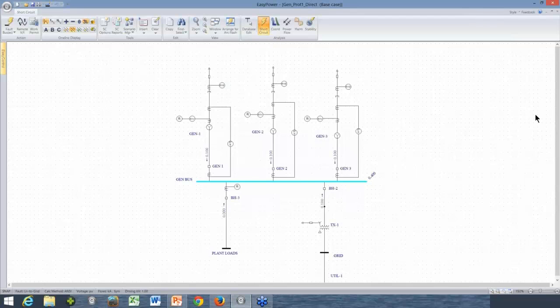So as you add units and ground sources, you have more and more fault current. So the alternative is to have a common resistor, one grounded resistor, where you might have to switch the ones that you're not going to be in service, and you do see that done in some parts of the world. It's not common in the US. It creates operational issues because you have to remember to make sure you have the right resistor in the circuit. But just remember that just because I have 100 amps here in my resistor doesn't mean this fault current is going to be limited to 100 amps if the fault's in the generator.